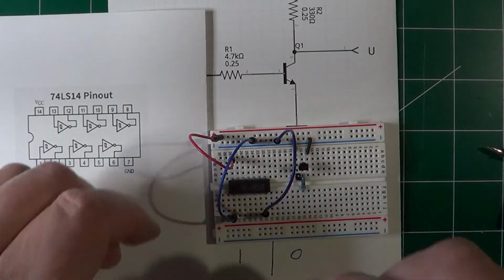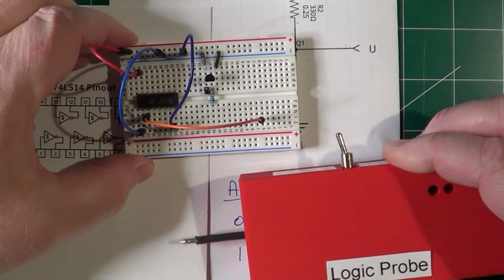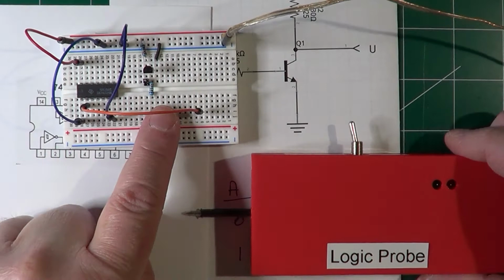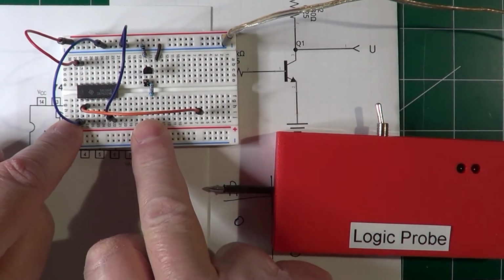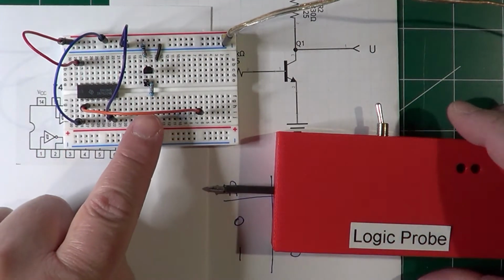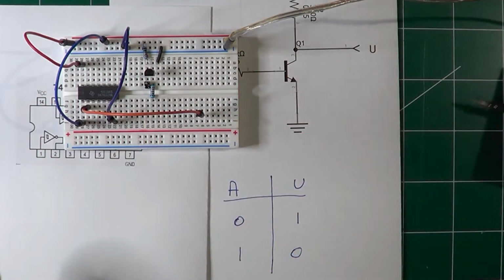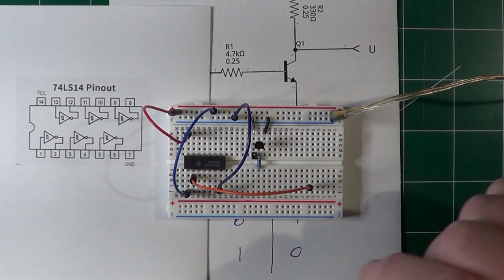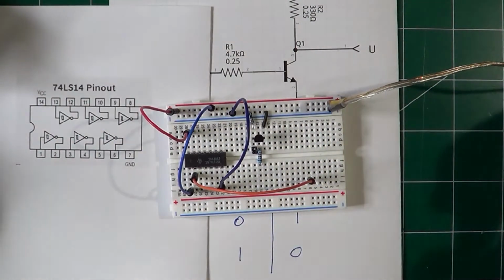I'm connecting another wire to it to easily touch it with the probe. The input of the gate is connected to 0 right now. If I now touch the output with the probe, the red LED shows up, which is the 1. If I now connect the input to the plus 5 volts, which is the logic 1, the output should go to 0. And yes, that's exactly what happens. You see, this IC is very easy to use because it doesn't need any external component, no resistors and no transistors. Let's now move back to the drawing board to talk about the next type of gate.